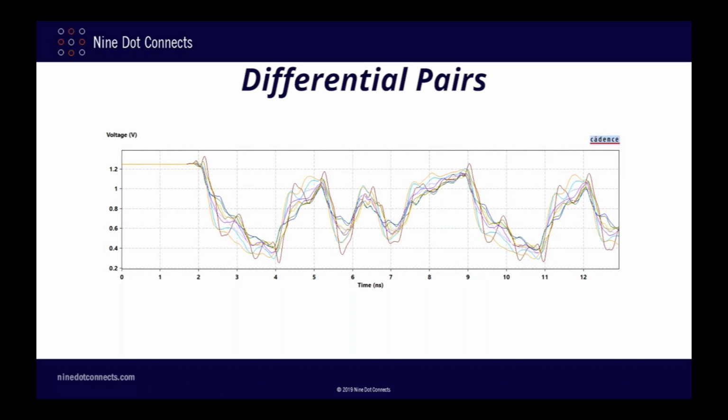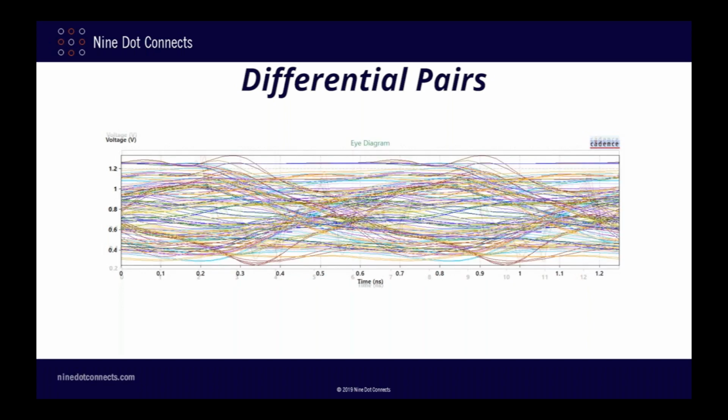So that gap really messes up the signal integrity, huh? As you see, the waveforms are all over the place. This is especially evident when we look at the eye diagram. As you can see, there is literally no eye opening at all. So we can pretty much guarantee that doing something like this will cause the design not to work.